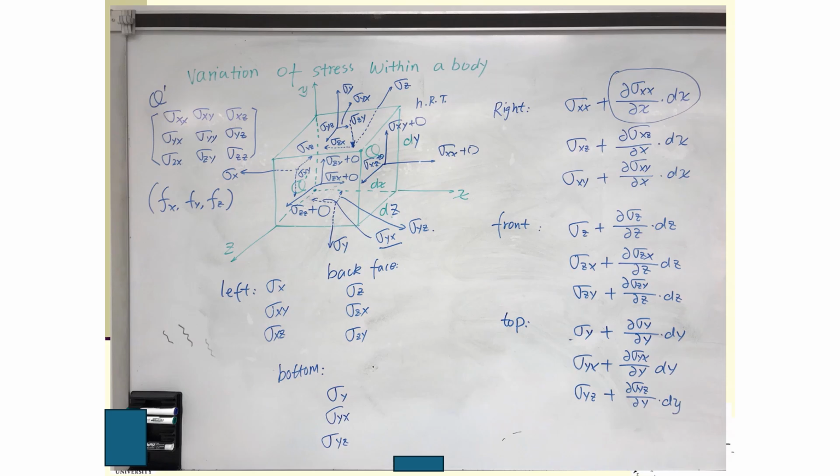You need to be very clear about this. We have force balance, we have moment balance. We do not have stress balance. Be very careful. Based on my teaching experience, many students make the mistake of thinking there is a stress balance equation. There is no stress balance equation.